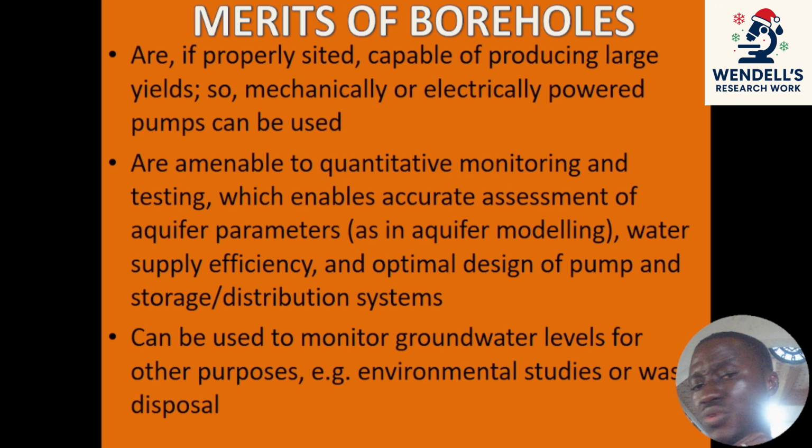Let's say you have a refuse dump somewhere. You have to get boreholes to monitor the quality of the water, because the leachates that will infiltrate can end up in the groundwater system. So this is it. The disadvantage is that you need a relatively high initial cost to do this work.